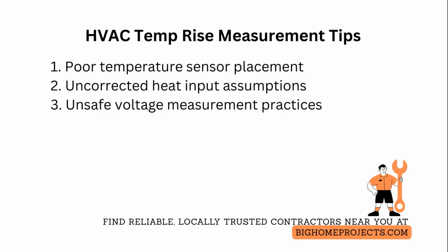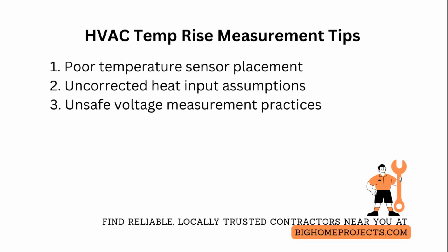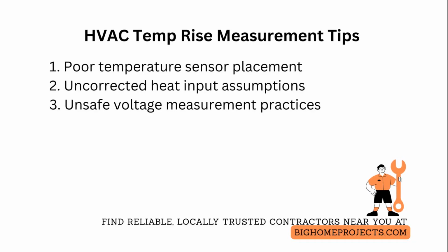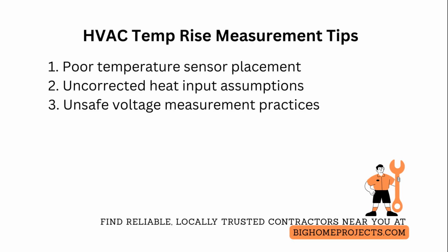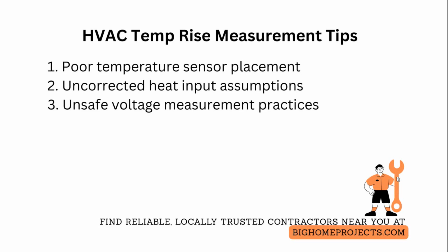One of the frequent issues is unsafe or unreliable voltage measurement that leads to arcing or bad readings. Fix by using insulated alligator clips, attaching clips before powering up, and never probing live conductors by hand while the system runs. Also use meter leads rated for the system voltage and record steady-state voltage concurrent with current to calculate true power.